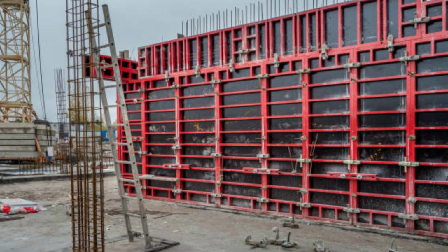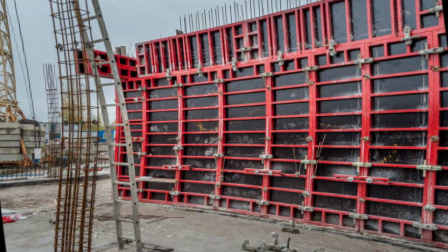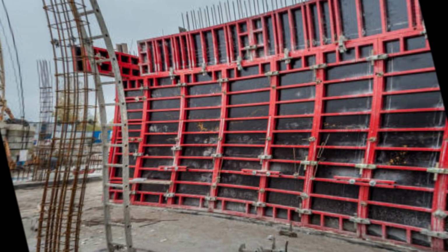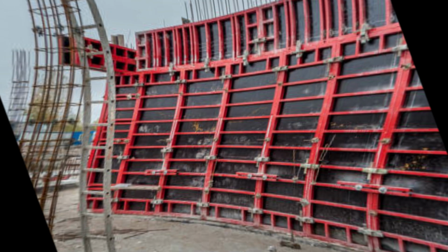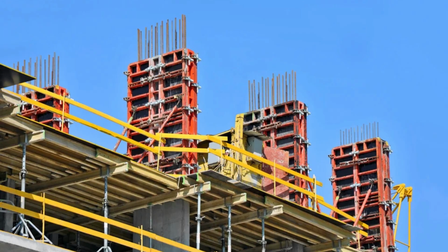Steel formwork. Steel formwork has become more popular due to its strength, durability, and repetitive reuse for a long period. Steel formwork is costly for small work but can be used for a large number of projects. Steel shuttering offers a smooth surface finish to concrete compared to timber formwork. It can be used for circular or curved structures such as tanks, columns, chimneys, sewers, tunnels, and retaining walls.